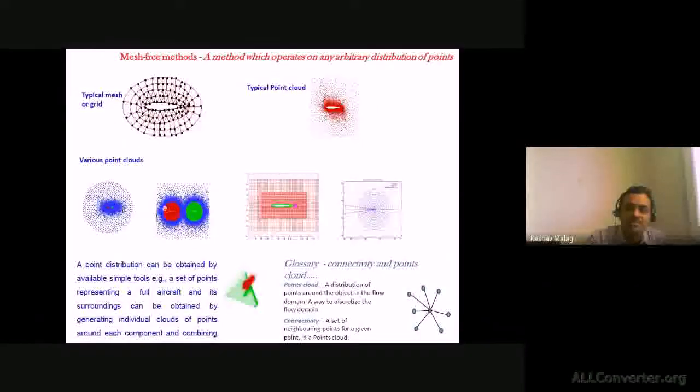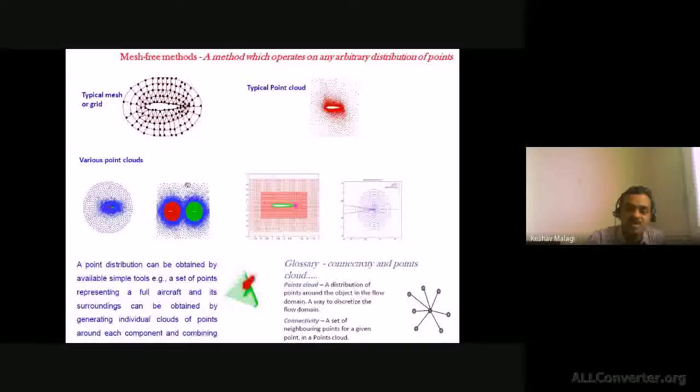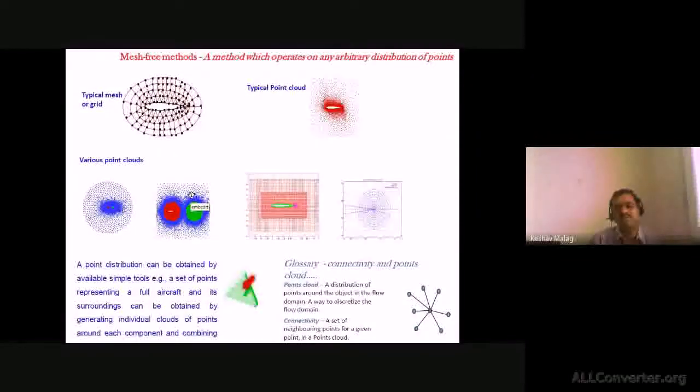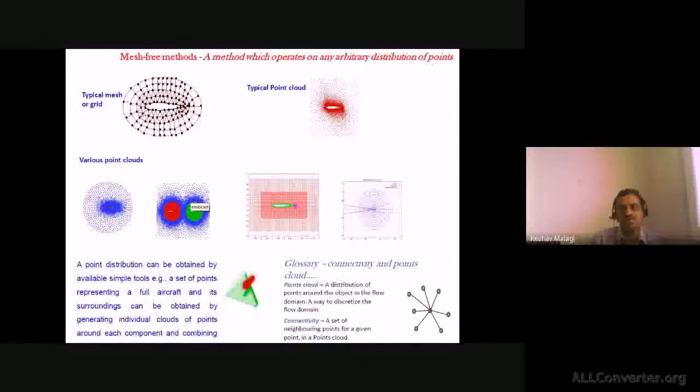Like if this red would have entered into the body of this green airfoil, you delete those points. Likewise, the whole domain will have points lying inside these two airfoils, and you blank them out. So at the end, you will have a cloud of points formed by grids around very simple geometries, which can be generated extremely fast without worrying about quality issues.